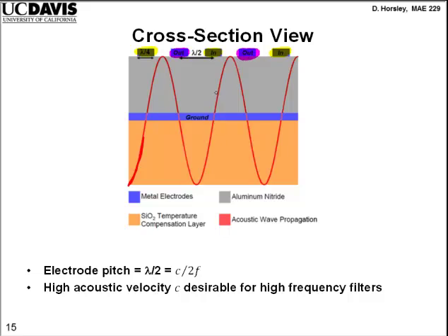And the idea, again, just like it's shown here, is that the electrodes are at 0 displacement points. Between the input and the output electrode, you have a positive displacement and a negative displacement, and a positive and a negative, because you can imagine how the field is directed.